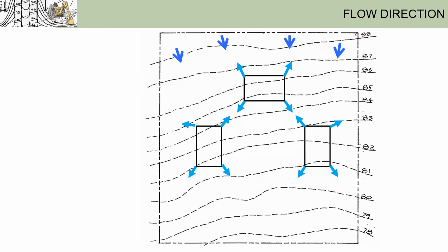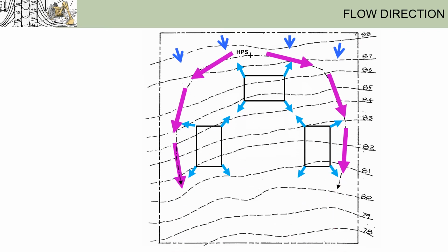And then next, just like grading for a single building, let's treat the three buildings as one big group. So you'd have a big swale on the high side of this group of buildings to run water across the site. And lastly, the areas in between buildings will enter into the big swale or flow downhill.